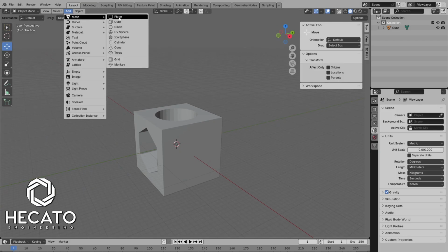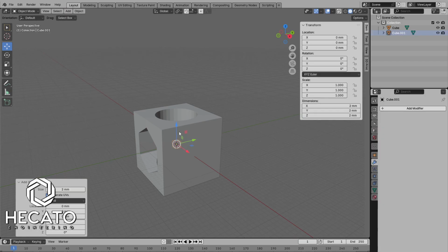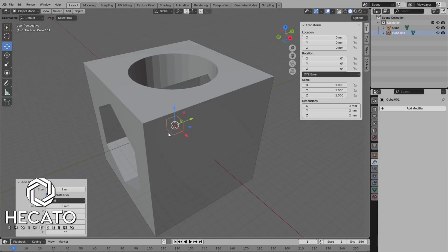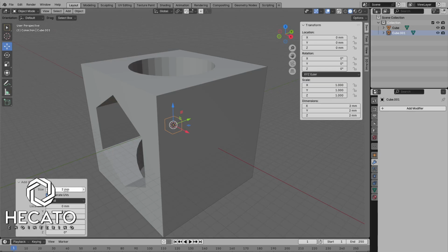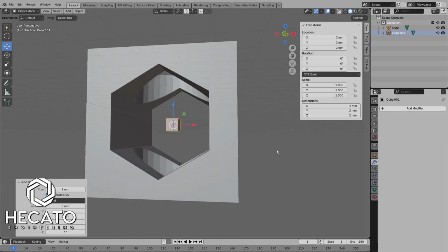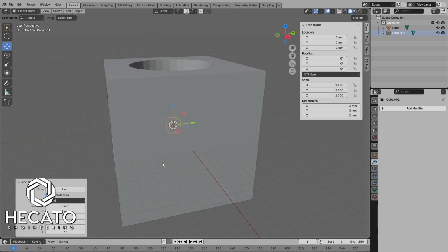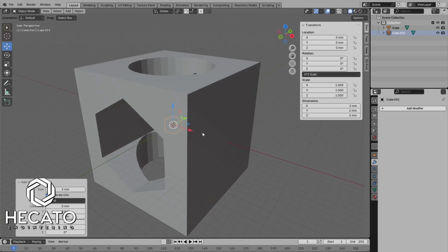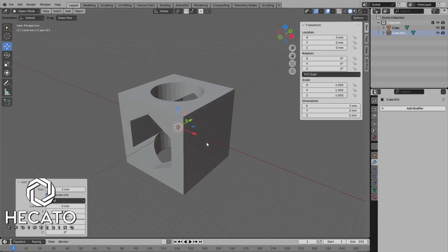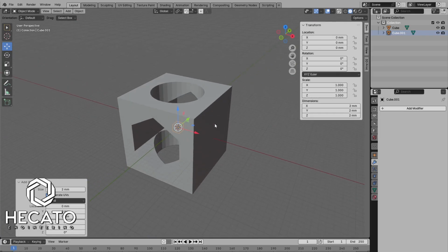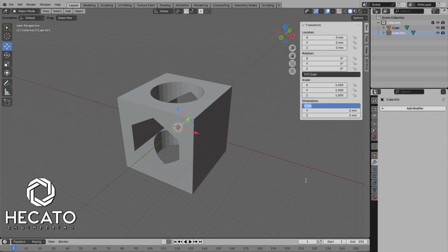The last thing will be to draw a rectangle here on this side. So we add, and we can also use a cylinder and type 4 vertices, or we can use a cube. The cube is here with size 2 by 2 by 2. We want it to be 13 millimeters, but diagonally. I will do it by hand for now. I'm going to scale. I'm going to size it to 22 in one axis. In this axis.